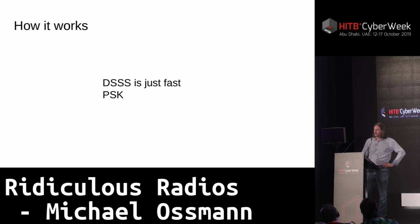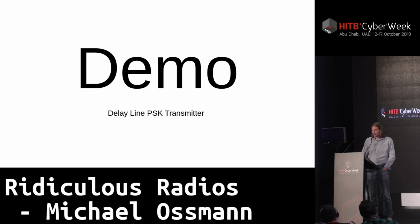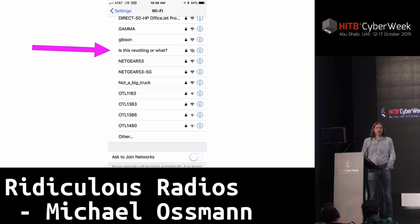That's all DSSS is. And so we said, hey, if we can transmit binary phase shift keying at 11 million bits per second, we should be able to actually emulate 1 megabit per second management frames that all Wi-Fi networks use. And that's what we did. And what we were able to do was actually produce beacons to spoof that a network existed. And I was able to pick them up on my phone, and see my phone thought that there was a Wi-Fi network present. That, in fact, was simply generated by shifting back and forth between those two delay lines.